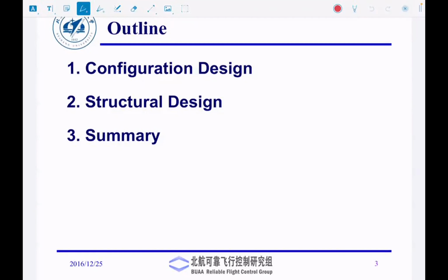This scaling would work as long as 3 fundamental similarities are maintained. And those similarities are geometric similarity, kinematic similarity, and dynamic similarity. And you will see the Reynolds number, Froude's number, all those concepts, when we talk about it. Those are dimensionless numbers. They ensure that whatever result you get from this small scale model, you would get similar result from the large scale model, and it can be scaled up. So we will talk about it, but later in the class, there will be something like Froude's number, something called the Reynolds number, and then there will be some proportions. So those are used for dimensional analysis.